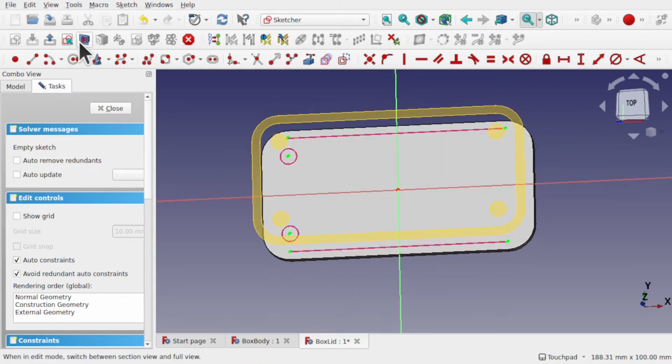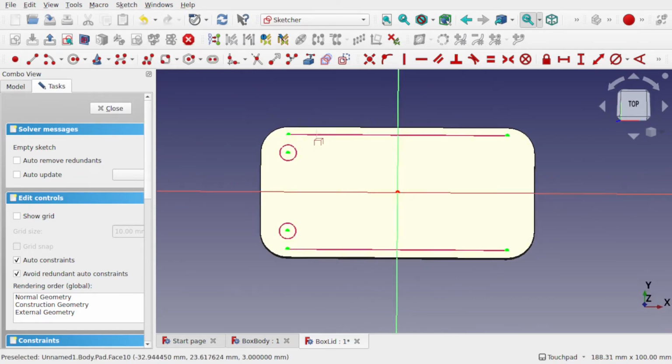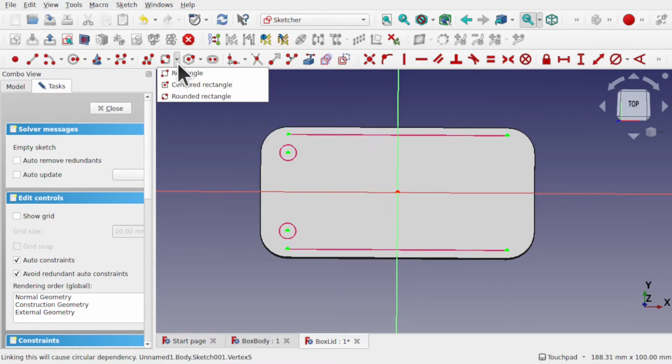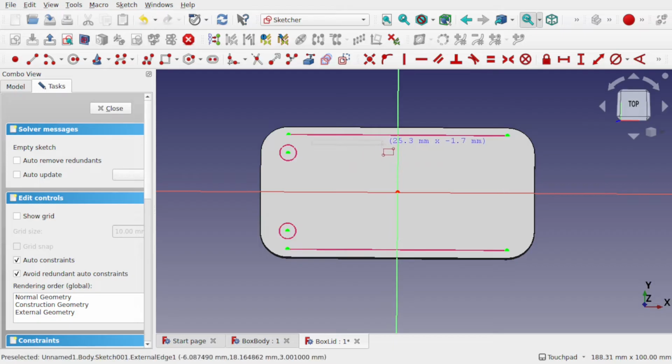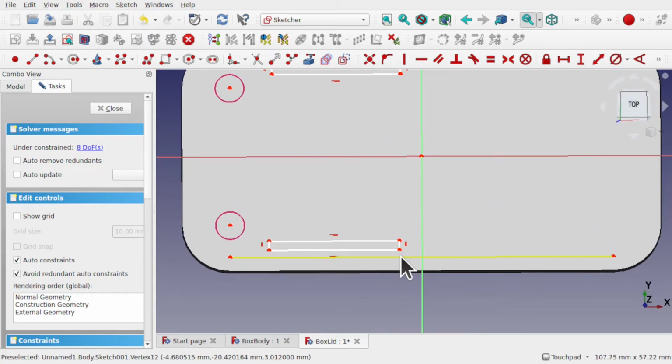And now I'm going to use the section view or sketch view section, so we get rid of that shape binder. So I'm going to use a rectangle, so standard rectangle, and I'm going to place a rectangle here and here, and these are going to be padded, but they're also going to sit 0.5mm away from this point.